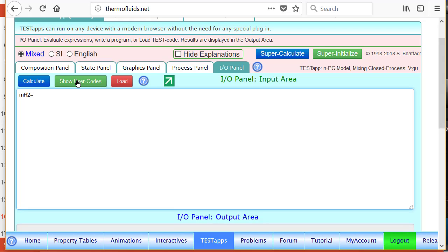So mass of hydrogen would be what? It's the mass of state 1 times the mass fraction of hydrogen in state 1, which is mixture A. And I noted that number down, 0.04379. So this is the mass of hydrogen, or its proportion at least, in mixture C, and the mass of CO2 in mixture C can be obtained similarly.